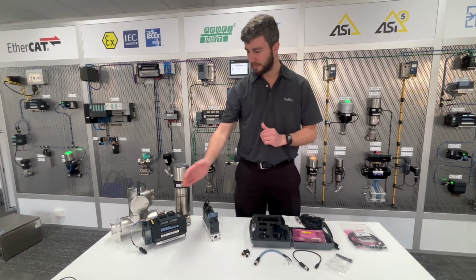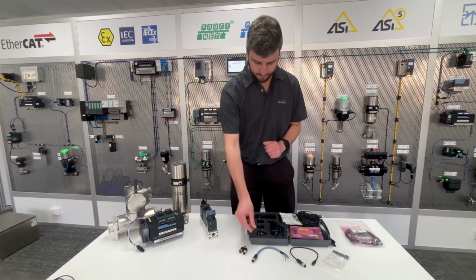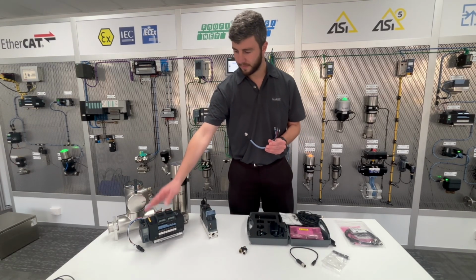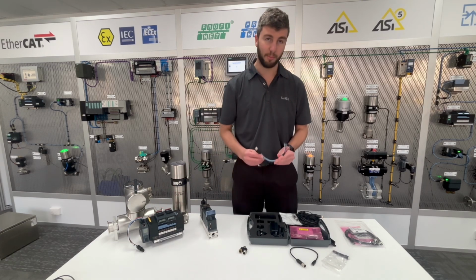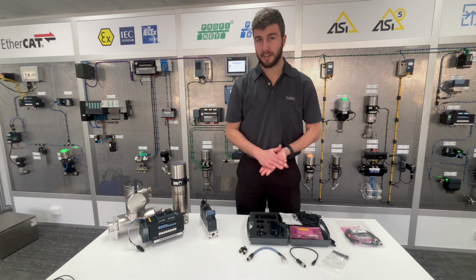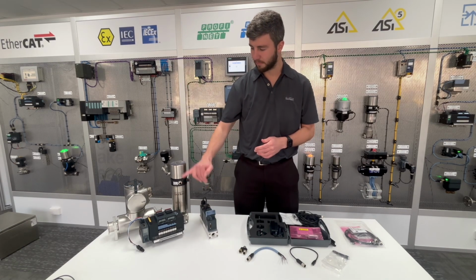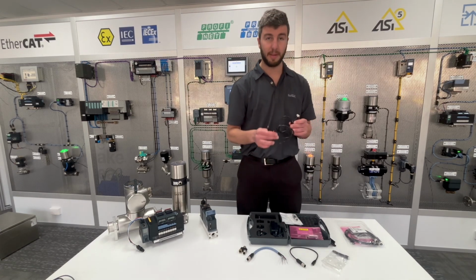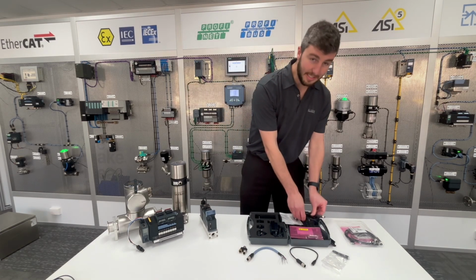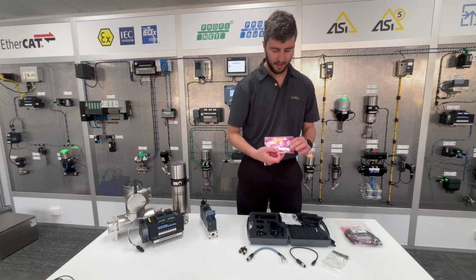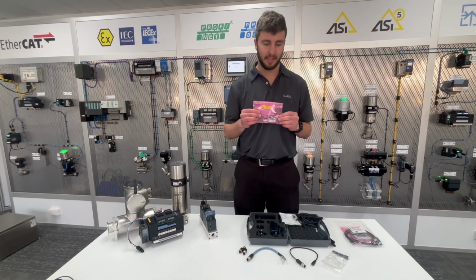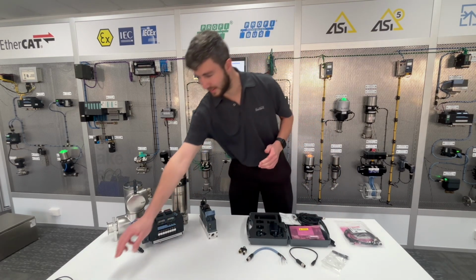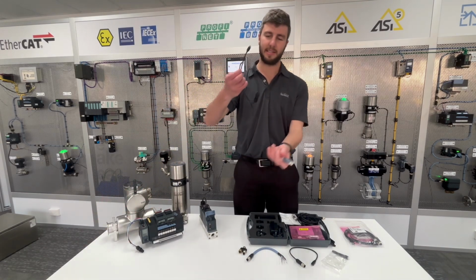For devices with terminal strips like our ME43 and 8652, it's important to use the flying lead to M12 cable to come into the terminal block and connect this to your wider bus network or to your Bürkert Communicator tool. Native bus devices will have a built-in M12 port that you will use the standard M12 to mini USB cable to connect. Once the cables are connected, you'll connect the other end of the mini USB port to the USB stick, which will connect to the PC so that you can connect to the Bürkert Communicator.